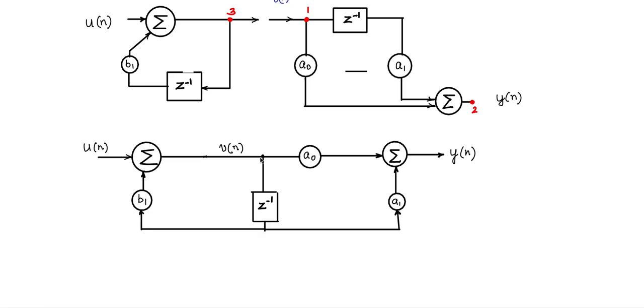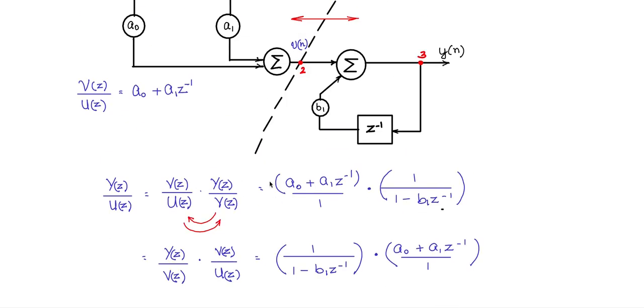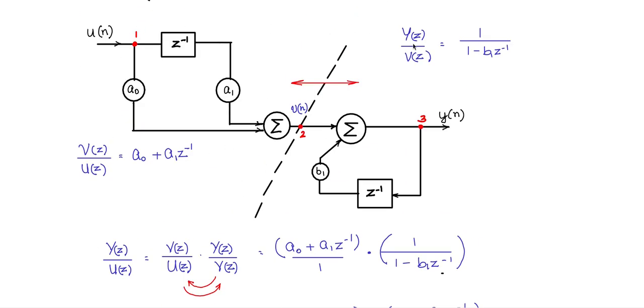So now you have Vk minus 1, and that is what is applied to this. I can bring in B1 here and A1 here. I am trying to put them in a standardized form. So this is B1 and this is A1. Now this is the filter. This is the first order filter, which is exactly the same as this.